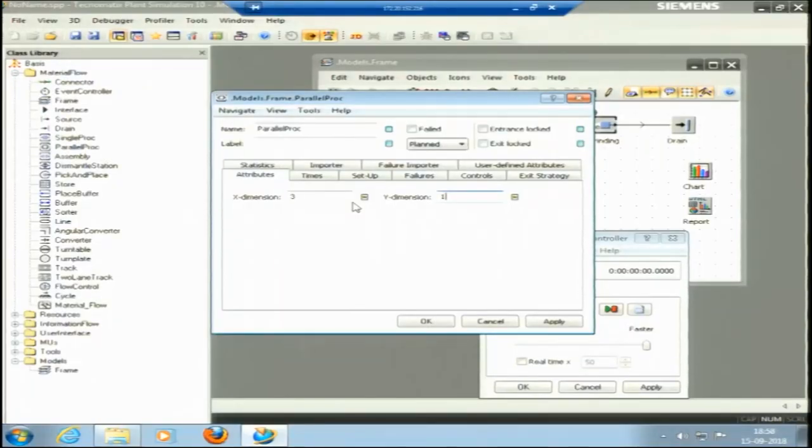When there is waiting or blocking, we can think of adding new machines, or of taking a few machines off. If there is a lot of waiting time, sometimes we can even think of doing some other processes, like I said in the case of the process layout. In a process layout, we have a specific set of machines in one section and another set of machines in another section. If we see the overall machine time and find that in this section there is waiting for 30% of the time, we can give them some other job.